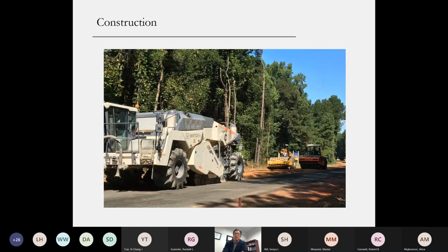Even though it was not required, the contractor generally performed the so-called premix. The purpose of this premix is basically to produce more uniform gradations, to identify some soft spots, and also to find utility lines that were not shown on the map, and then to address these issues before the actual FDR process.